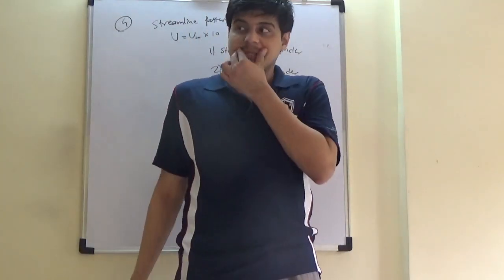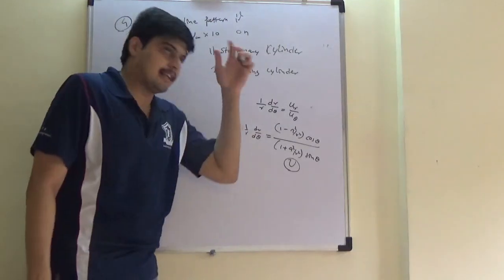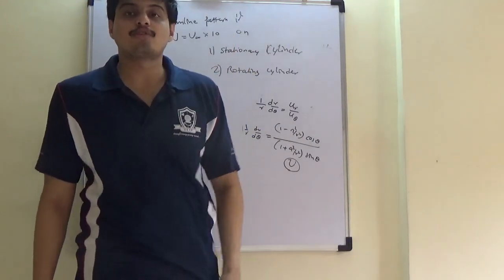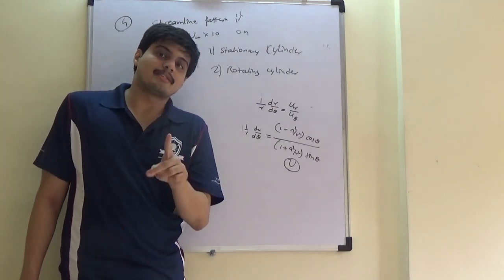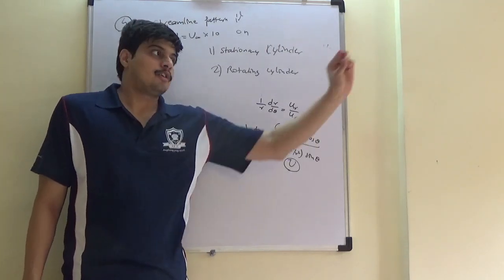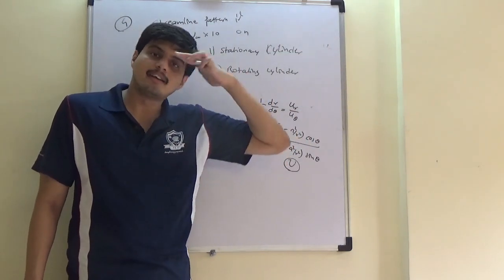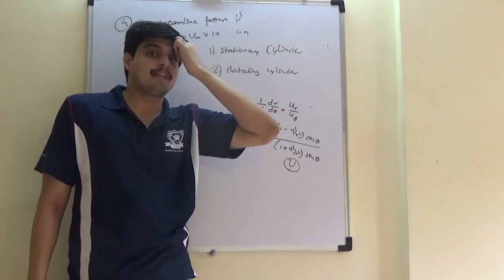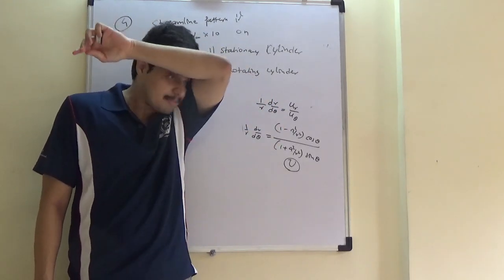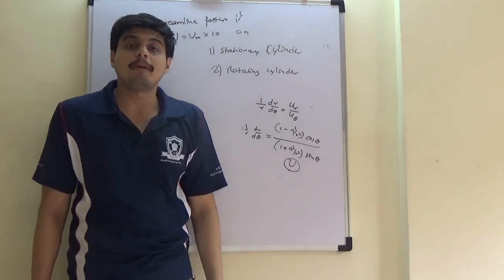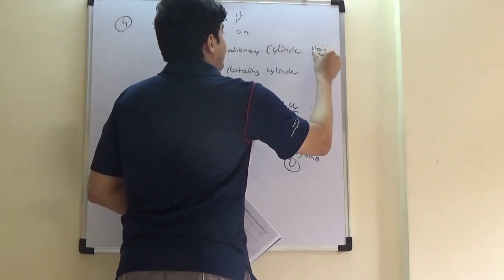Just by moving faster, the pattern of pressure drop on the cylinder, because of the symmetry, is not going to change. So the streamline equation remains the same. You move at 20, 200 or 2 meters per second, the photograph of streamlines, the lines formed by tracking the particles following a specific path, would be identical. So, no impact.